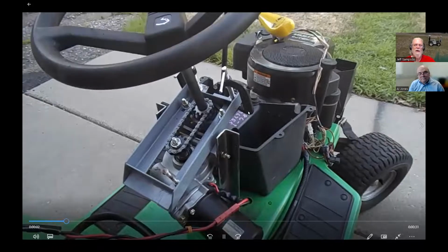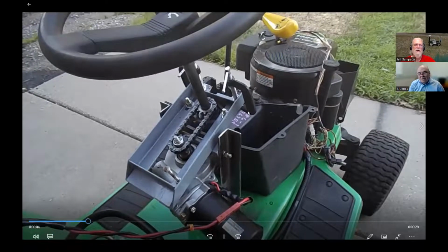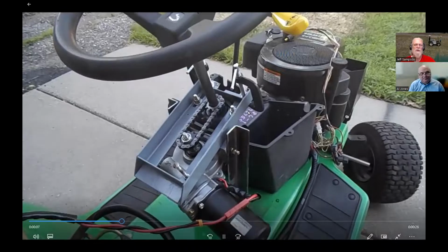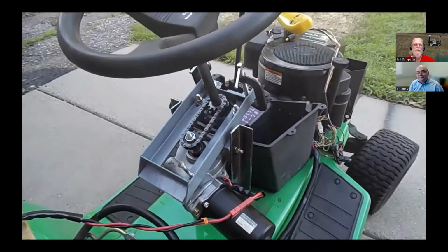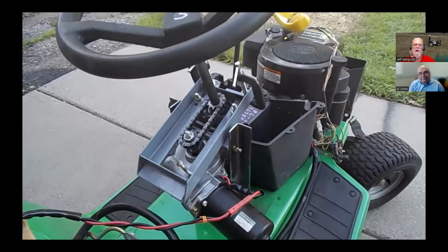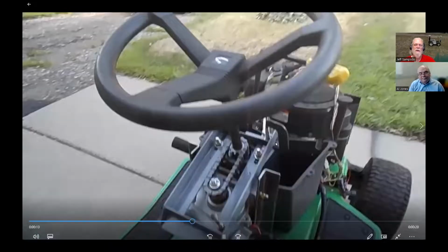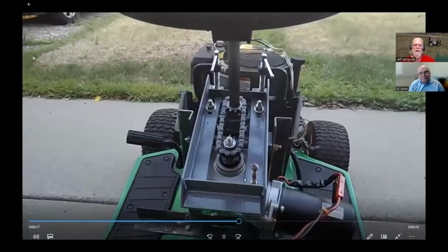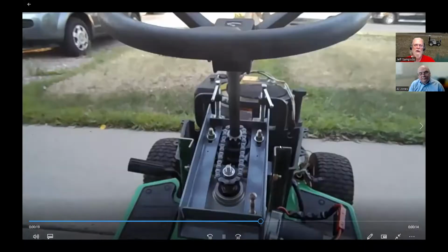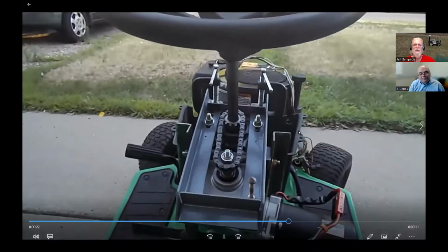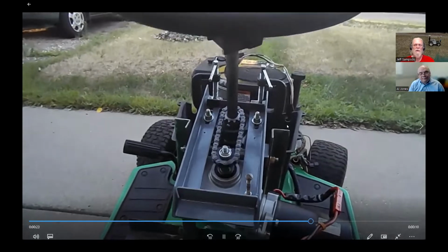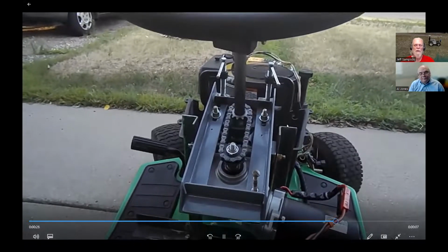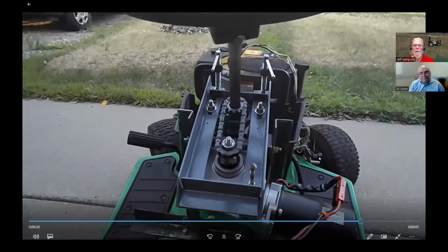So I assume you're not getting audio, but it's just no audio, but movement. If you watch the YouTube video, when I first change direction, you hear a big clunk, and I think that's the pinion gear at the bottom of the steering shaft and the big gear down the bottom. It's just the teeth aren't meshing as well as they should. So there's simply a different view of that same thing going on. And it's almost done here.